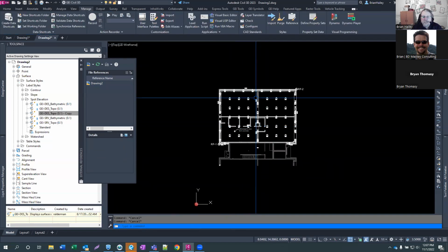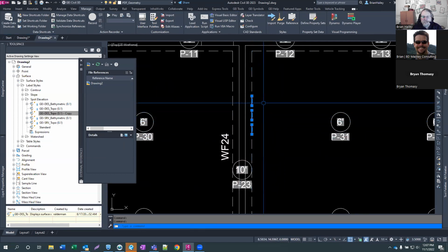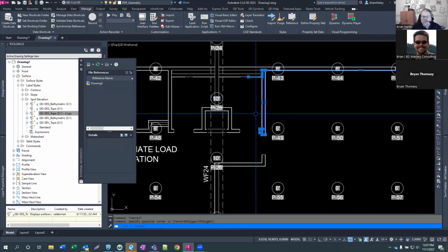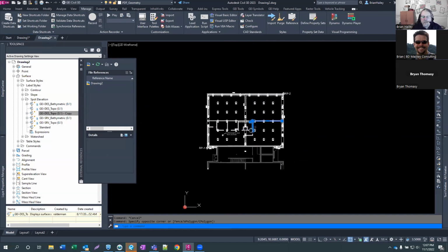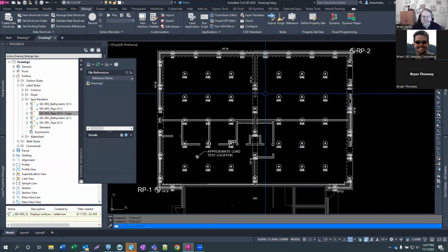Now it's not perfect. Line types don't exist in a PDF. So these are individual pieces of line. But you've got the line work. And you can now use your hardware, aka interns, to clean it up and make those dashed lines into an actual line. And yeah, that's all there is to it. Now, this only works on vector PDFs. All right, so if your PDF is a scanned PDF, this ain't gonna touch it.